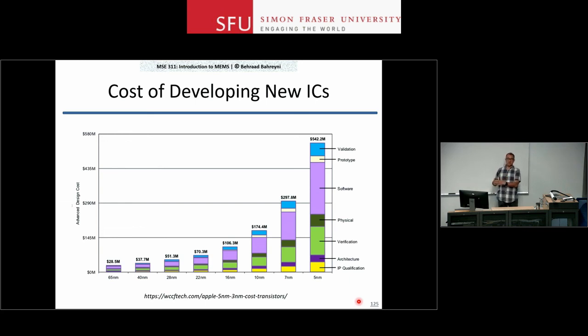And I sell the rest of the chip as a 9-core processor. That's actually done very commonly, and that's one of the reasons sometimes that you need an odd number of cores, a weird number of cores on a processor, a 3-core processor, a 7-core processor. It's most likely a chip where one or more of the cores on the original design didn't work.